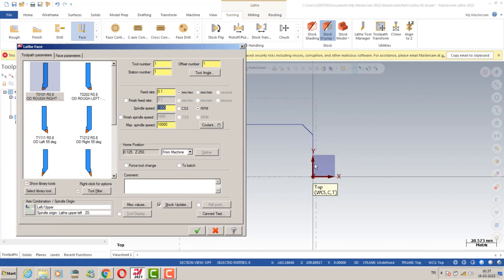So it means that if we use constant RPM in the cutting process here, we're going to get better surface roughness here, but not good surface roughness there, because we're going to cut, for example, 150 multiplied by pi.